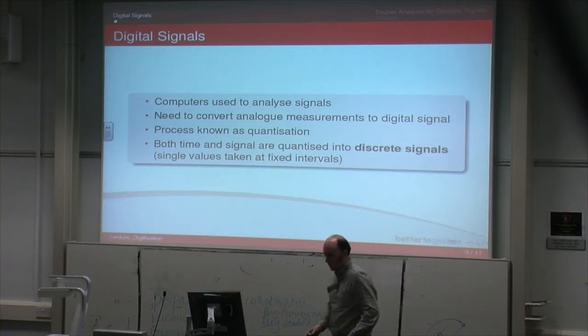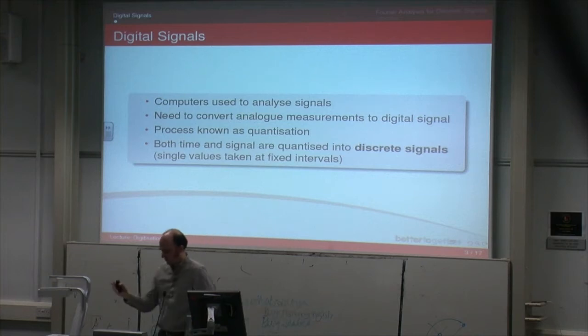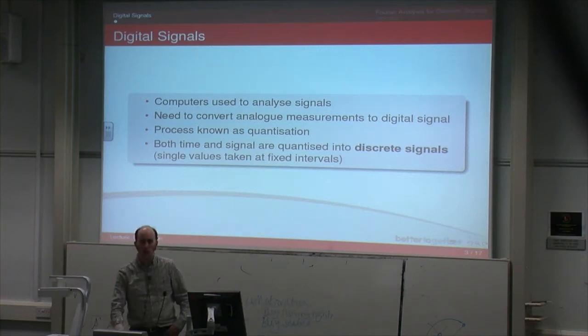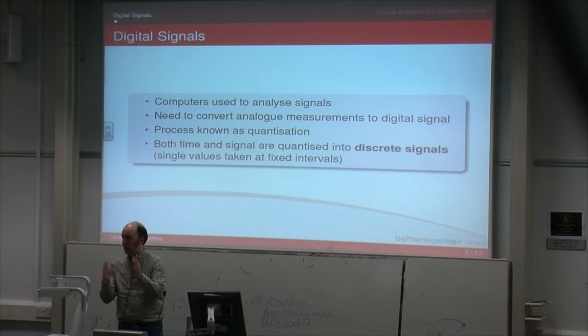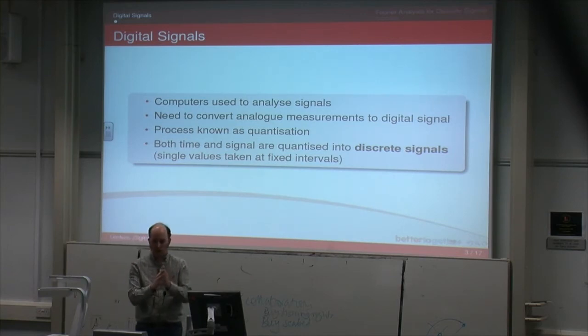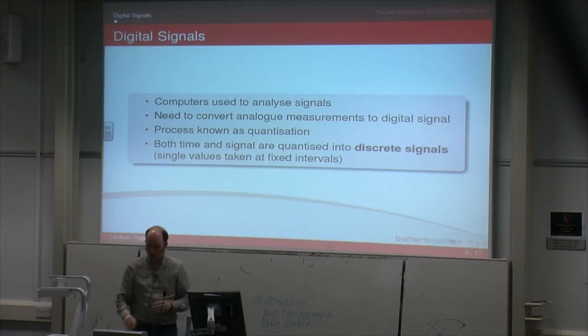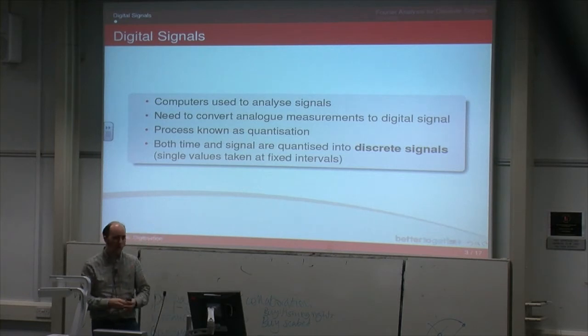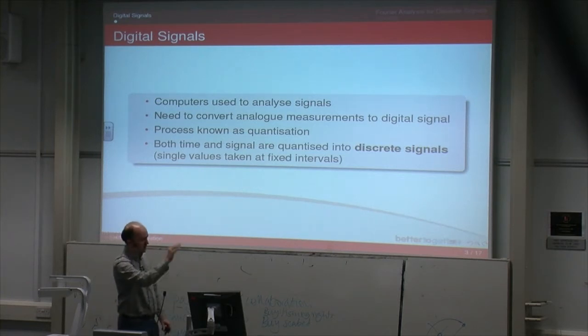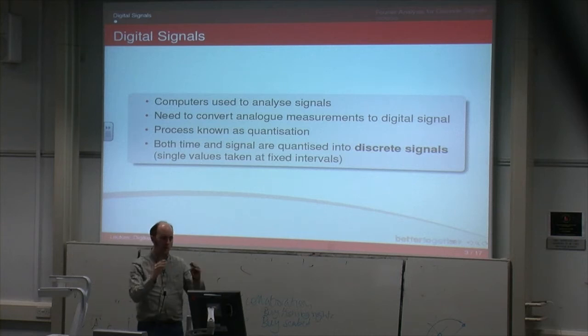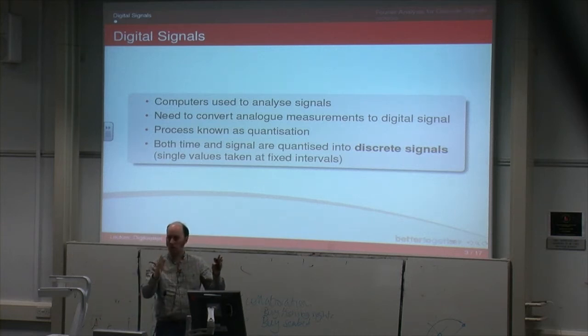Okay? So when you've got your system, let's say it's a mass spring damper system, and you've got a transducer attached to the thing that's moving, okay, and that transducer will measure its movement, give you an x value in a sense for displacement. Now, if you were to draw that by hand, you would draw x as a continuous line, because between the limits of its movement, your line can be associated with any point along that movement.